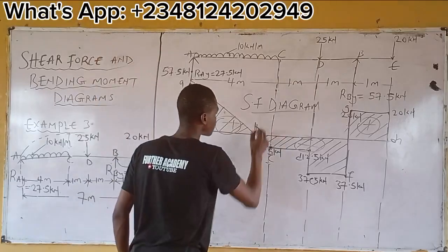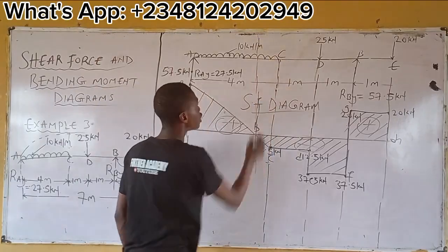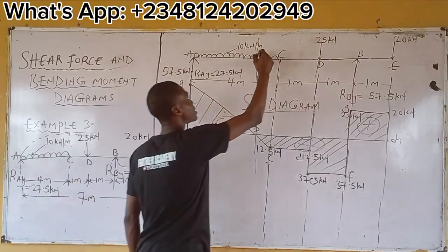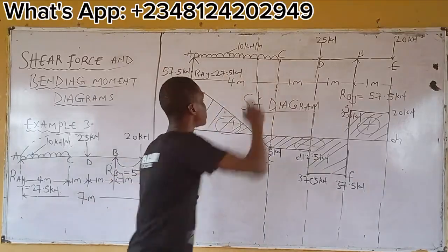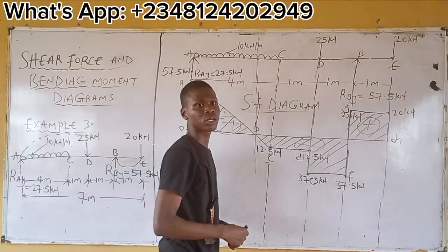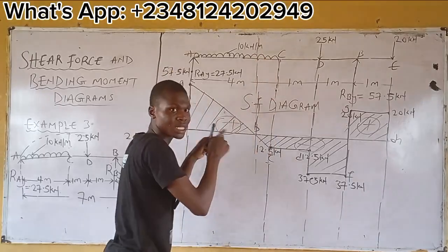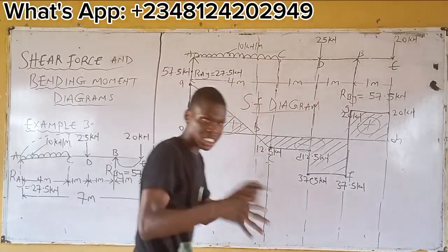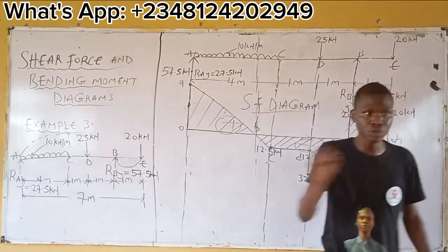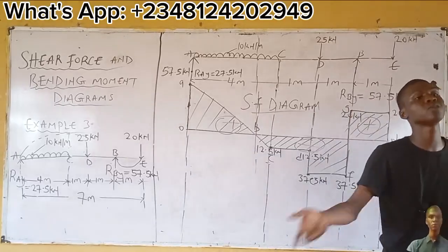By the time it's sectioned, you have this beam left. Now, take shear force. The shear force you've been doing, take shear force at this point. You taking shear force at this point, it means from A to that point, X meter. That's X you want to know. So take shear force there, you get the value of X. Meaning any value you'll be getting becomes the value where maximum bending moment will occur.